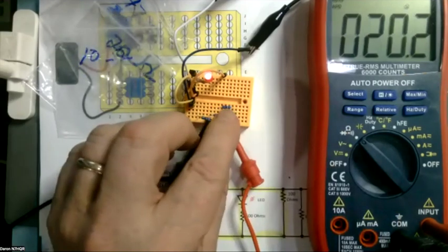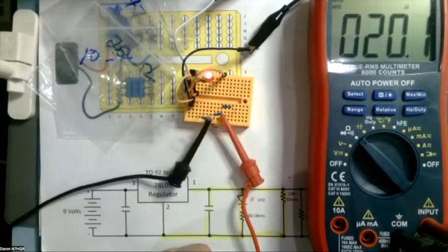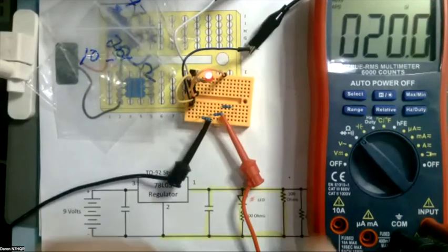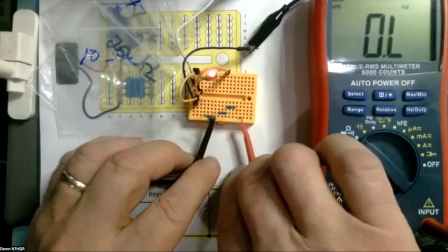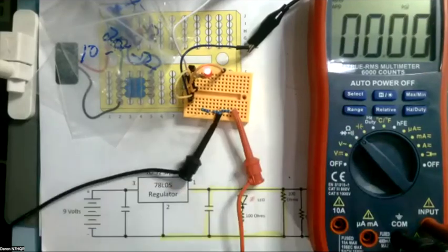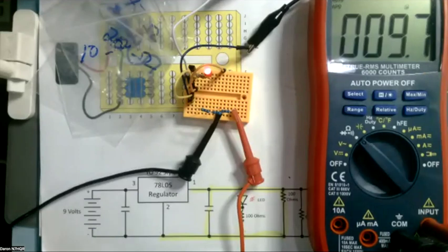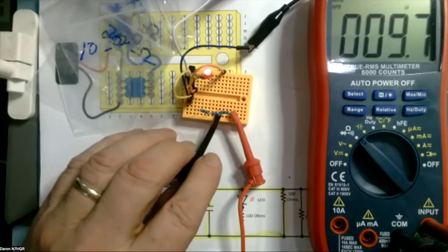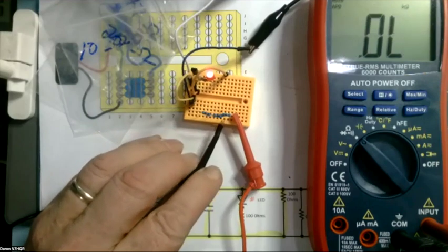And to check resistance, you turn this to ohms. And the next one is a 20 ohm resistor, and that looks good. Boy, those are pretty accurate. They've been within 1 point each one. And the last one is a 10 ohm resistor. So we'll look at all three of those in series.